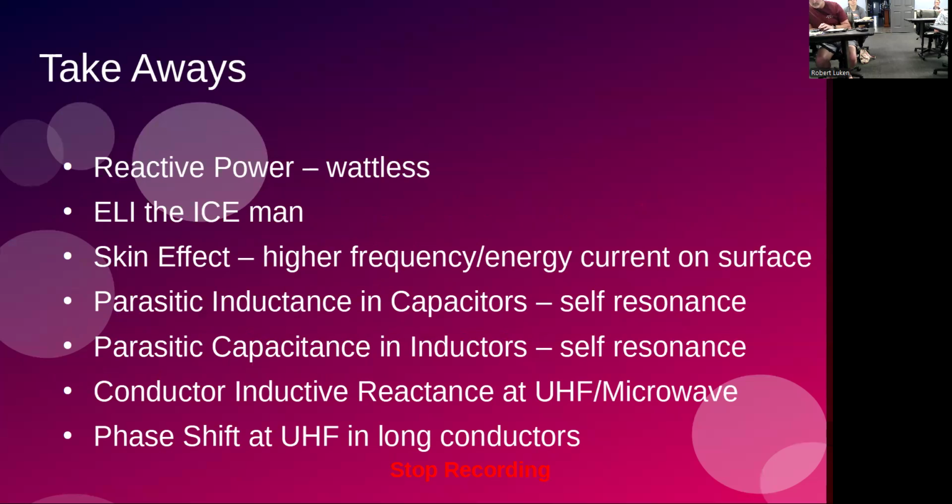Skin effect goes up with frequency, and it can affect capacitors as well as inductors, but mostly capacitors, which is why they don't work as well at very high frequencies, especially electrolytics. And you care about phase shift when you're doing UHF and microwave things because of the length of the conductors, not only the inductance, but just the length of it starts to approach the wavelength of the signal itself.